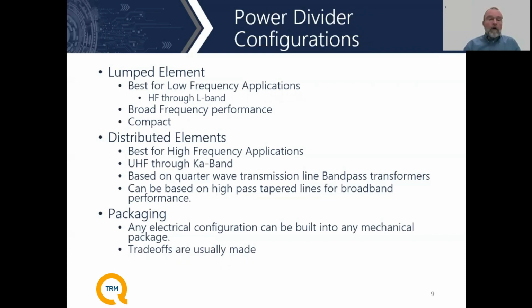Distributed elements are really the construction of choice for high frequency applications, really UHF through Ka band. They're based on quarter wave transformers and high pass and band pass filters. Therefore, they tend to be band specific, but they can perform very well and have good, robust applications. These can be built in either surface mount or connectorized packaging. A lot of variability here as far as how we can build these.